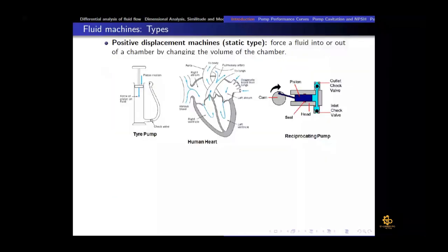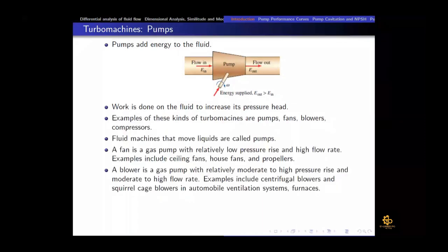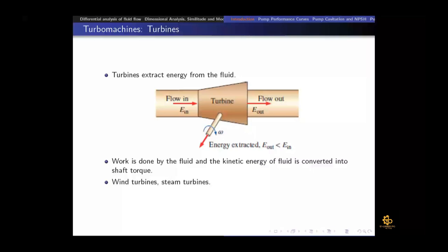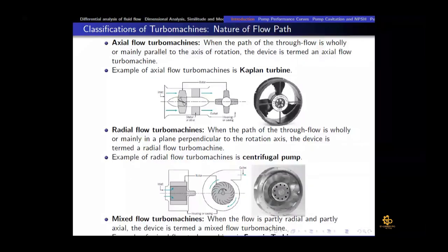we were at this point. Okay, so we talked about axial flow turbomachines, radial flow turbomachines, and then we have another one which is mixed flow turbomachines. In that the flow is partially radial and partially axial. So we call it a mixed flow turbomachine, and the Francis turbine is one of the prime examples of mixed flow turbines. We would discuss it in detail when we discuss the Francis turbine, so you would understand that.